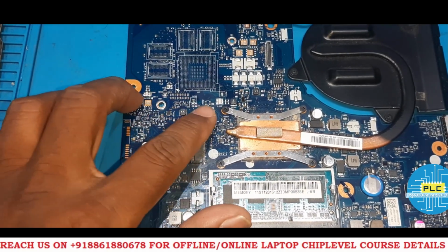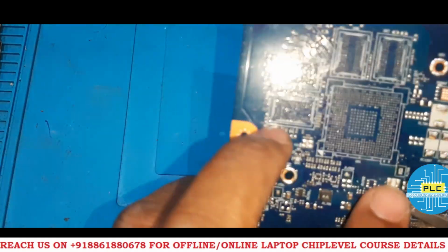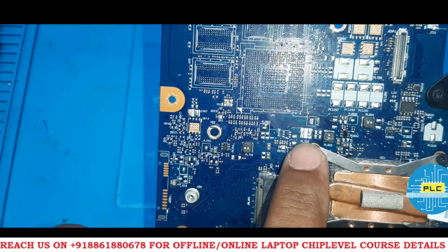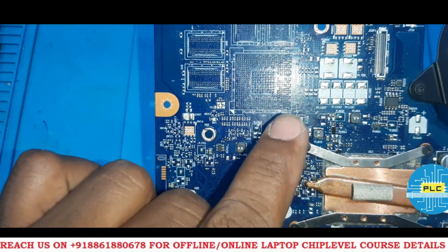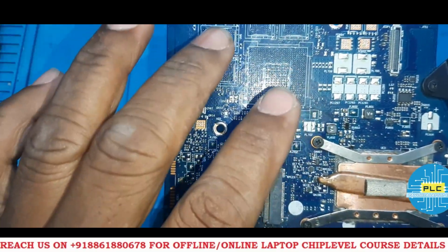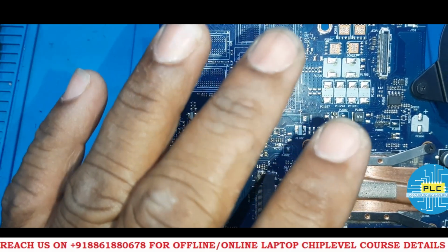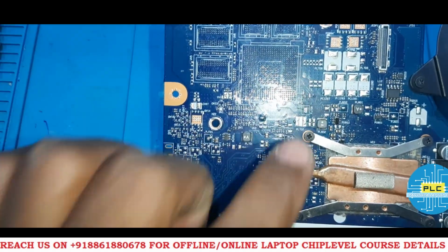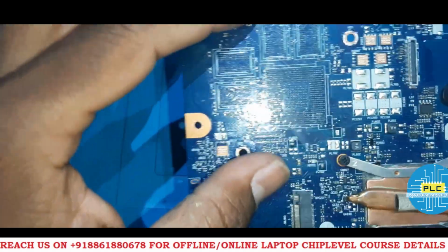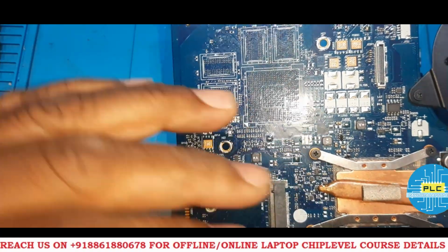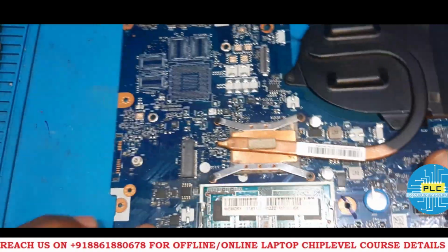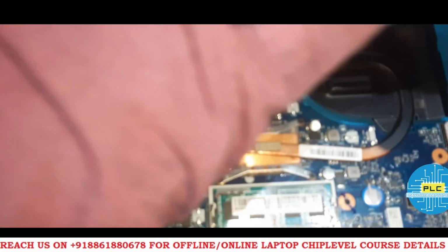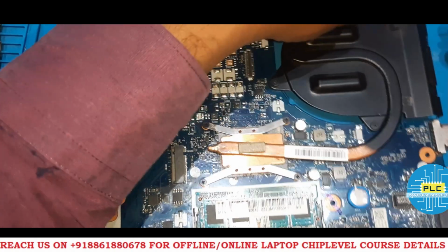See guys, next I removed PJ709. See here, it's PJ709. Actually there is no graphics chip, but I removed it here also. So what voltage are we getting here? In case the chip is there, in that case it's 1.05 VGS voltage. It's graphics, so we will get 1.05 volts, but now there is no graphics chip. Still I removed it for checking purposes to see what it will take. Previously what amp was it taking, 0.166, right? Now I'm going to connect this one, and we will check what we get one by one.